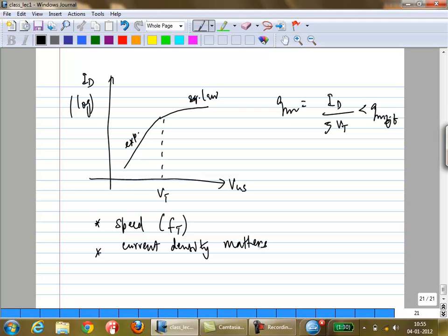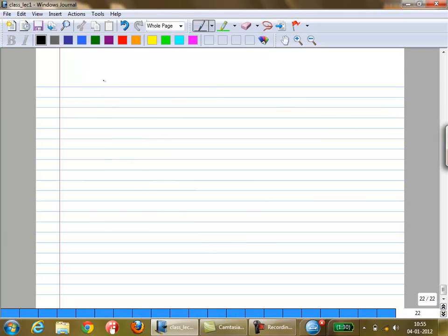So I guess one last thing I wanted to touch upon. I assume you all know this; it should just be a refresher. When you start analyzing a circuit, first do the DC point. Always start off with the DC point. To analyze the DC point, you always use the large signal characteristics. If it's a MOSFET, you use the square law. For bipolar, you use the exponential characteristics.